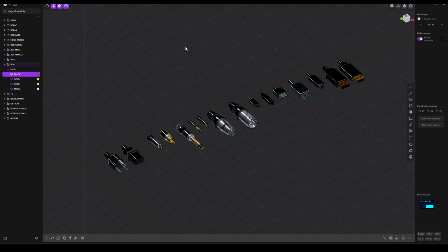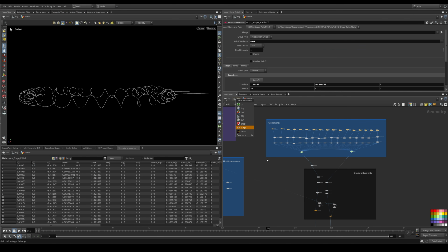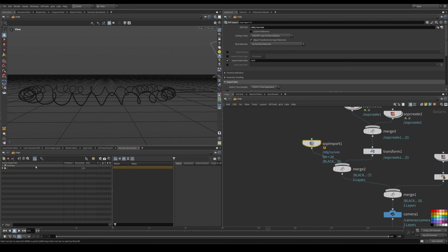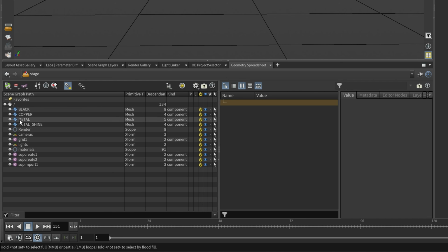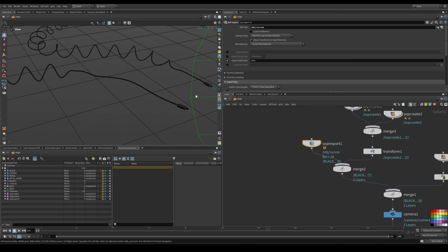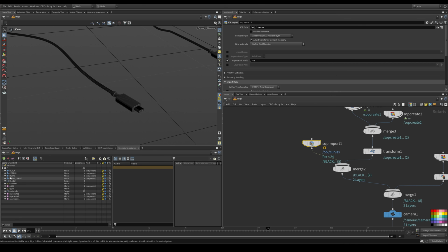So when they come into Houdini and you feed them through Solaris, so if we take a look at Solaris real quick, when they come in here, they come in as the full shape. So we don't need the actual groups anymore. So what we can just do is drag the entire shape. And because it's on the root and it's already linked to a color, when we start switching our inputs for our different curves, the colors will automatically assign to the new pieces of geometry just because they're already on the root with the same name.